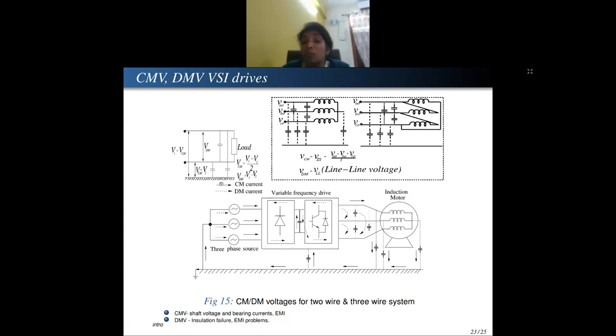And this will be more visible if your switching frequency is higher. Why? The capacitive reactance Xc is inversely proportional to frequency. If the frequency increases, the capacitive impedance will become lower and lower, so it attracts more current towards that. So the parasitics at higher frequency will inevitably affect the system.